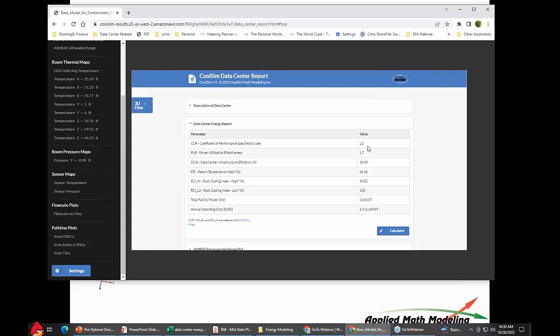Now, for those of you who are following ASHRAE, and I think Henry Amistadi might be with us, we worked together on this. He's on the 90.4 committee, and there's work going on to turn this number right here, COP, into something called MLC, mechanical load component. They actually use it as an inverse of COP, so it's a fraction. But nonetheless, it is the same kind of thing. It is the measurement, or in his case, the prediction of the total energy required to operate the data center compared to the load in the data center, IT load, really thermal load.